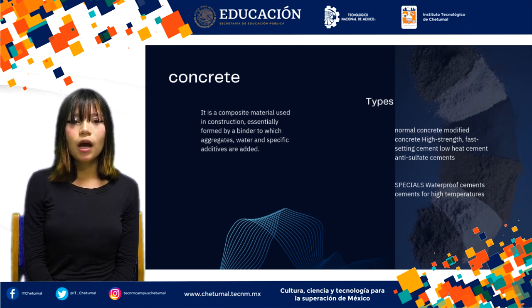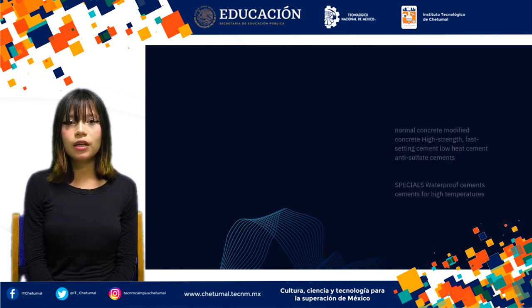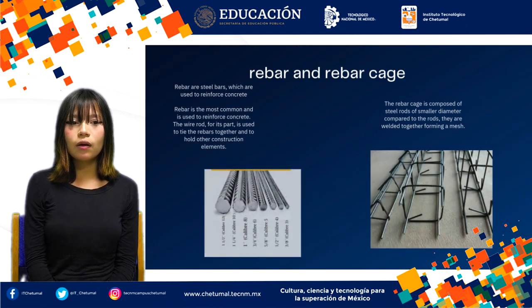Low strength concrete is used since it does not bear significant loads. Placement of the base. A concrete layer approximately 5 to 10 centimeters thick is poured at the bottom of the trenches. This creates a flat surface and prevents soil moisture from affecting the foundation. Functions of the base. Besides leveling, the base protects the reinforcing steel that will be placed later, preventing direct contact with the soil. It also reduces the likelihood of deformations in the foundation due to contact with the natural ground.